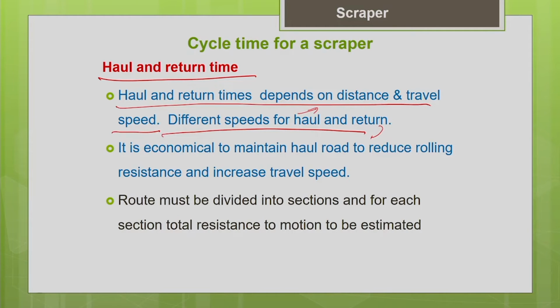It is very important to note that we have to maintain the haul route. We have to spend some effort in maintaining the haul route of the project site. You can maintain it with the help of a grader or a bulldozer, and using water trucks. You have to sprinkle water and maintain the moisture content in the haul route, so that you can control the dust and improve the visibility at the site.